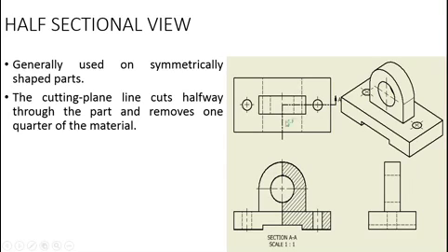So let's look at the drawing on your right. Here we have a cutting plane, which starts from this point here, goes inside the drawing, and then at the midpoint it turns and comes back to this side. You can see here we just took out 1/4 of the drawing. From there to there, this side here, will be the 1/4 of that drawing.